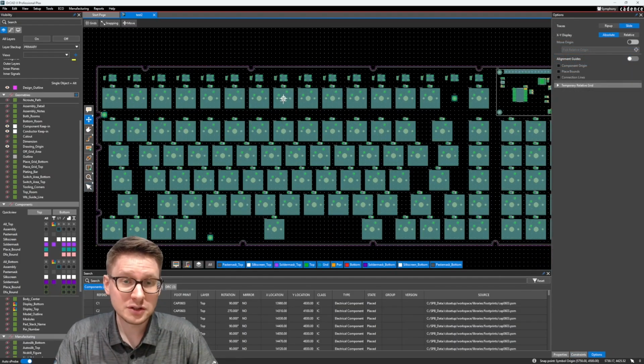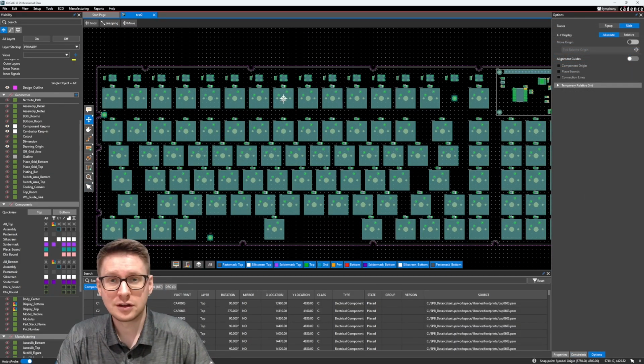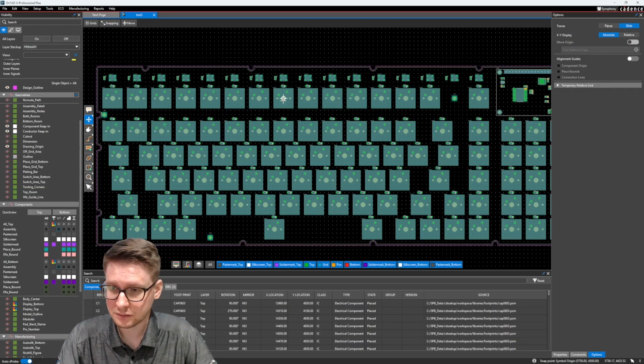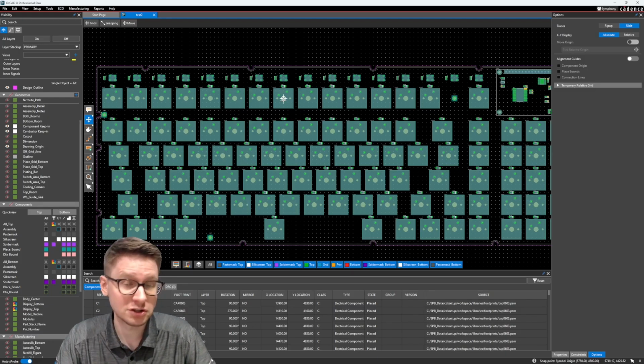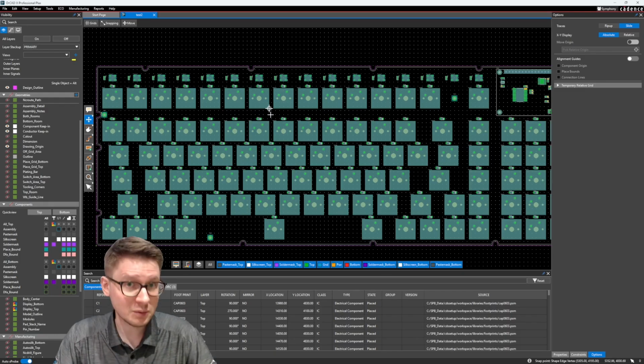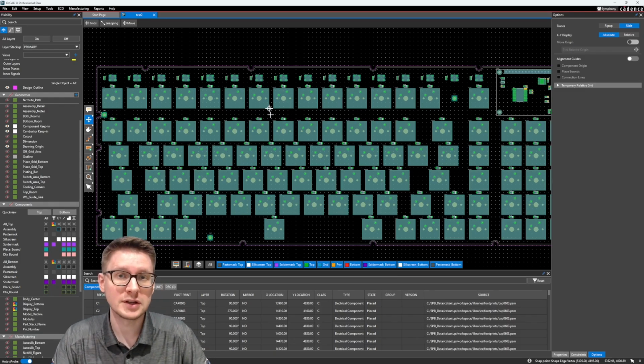So when you're doing your constraints, you kind of want to have an idea of all of the constraints for your design or how your design will behave while you are doing the layout. And so you're not caught by surprise by, for example, a wrong via showing up out of nowhere or some strange line width, right? That doesn't mean that you can't adjust your constraints as you go, right?